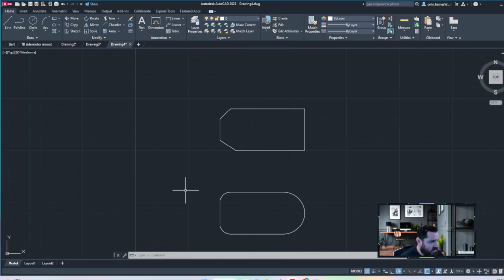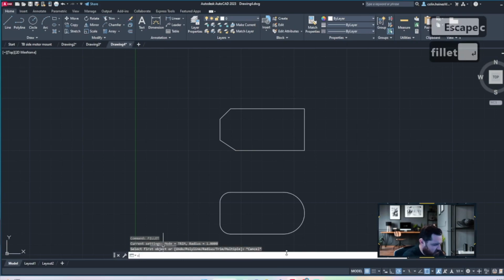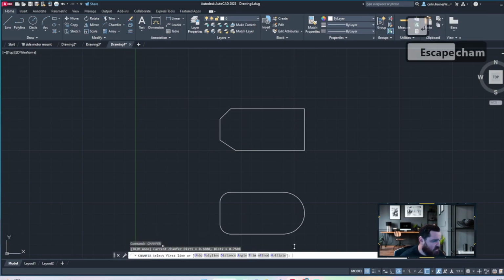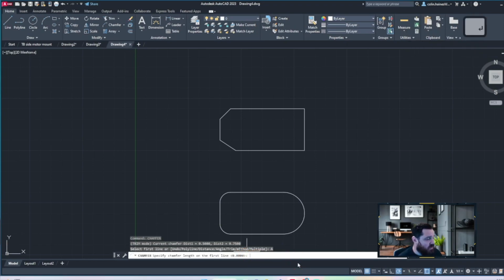And lastly, let's go ahead and make a perfect little right angle here with our final curve. So fillet, and this time, oh, whoops. No, we want chamfer. So this time around, we're going to go ahead and use an angle. So it is going to ask us for the chamfer length of our first line. I know that that's 2 units and I want to make it a perfect angle. So I'm going to use it in its entirety.